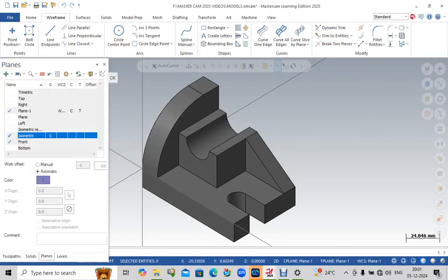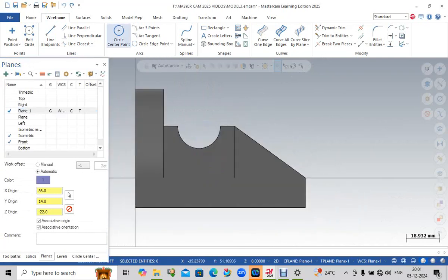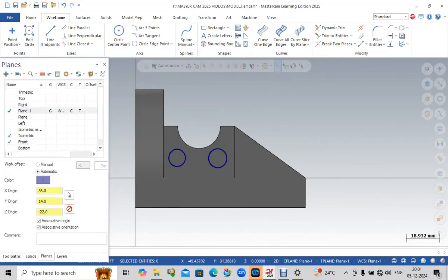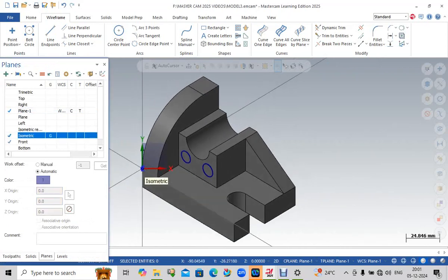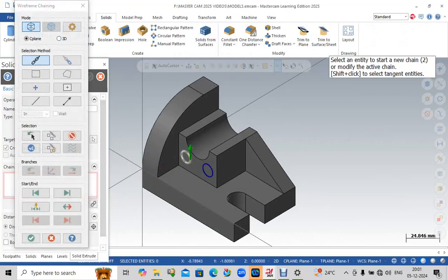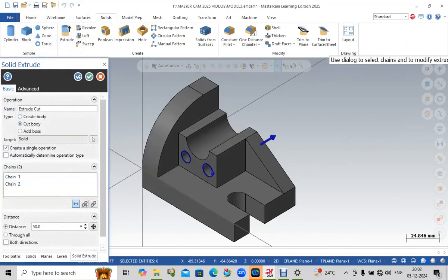I go to save it. Then go to geometric view. Then I can create a circle. Then I can extrude some portions, whatever you want to do. After that, selection is more important here. Cut body, opposite directions, through all. Okay.